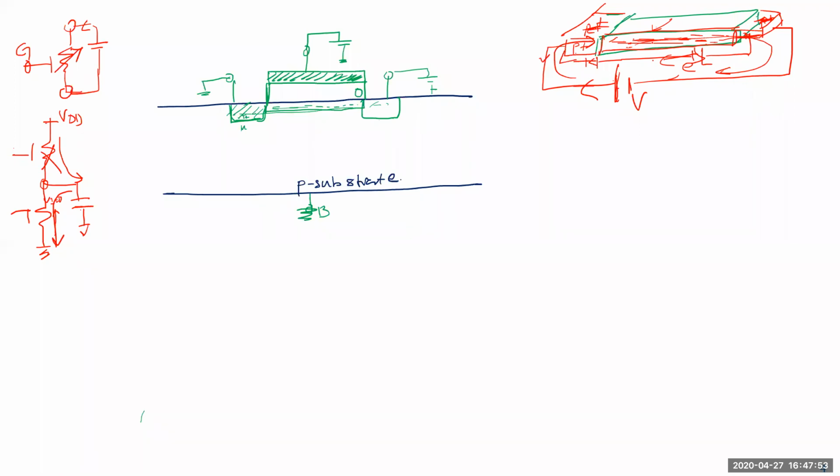But you won't get a huge amount of current because you just don't have those carriers here. When these carriers flow in this direction, somebody has to replenish them here, but there's nothing to replenish them. There is a charge here, there is a charge here, but the P plus will not take it. There'll be some diffusion, but that's a very small amount. So that will not conduct. So the short answer is yes. Well, the short and the long answer for metal is yes.